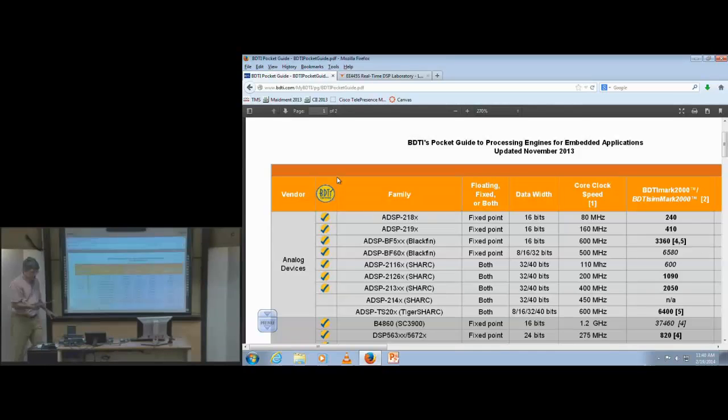A core is something that's not delivered in silicon. It's delivered in hardware description language that can be synthesized. So the Verilog, probably more likely, or VHDL is another option, that can be synthesized directly into a custom design. The chips are what you buy, right? Physical chips. All right. So here are some companies that work in this space, and the number of companies has decreased with time. I'll tell you that. There's been consolidation in this business.